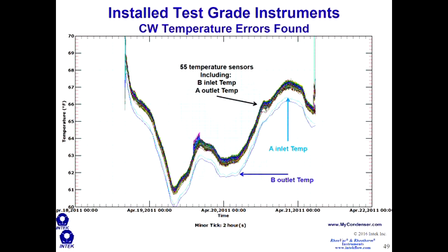Oh yeah, thanks, Colin. One thing to point out is that this data was obtained during no load conditions. So the cooling water is flowing and there's no duty to the condenser. That's the time to do this type of analysis. There's water flowing from inlet to outlet, no duty to the condenser, no temperature rise, and that's where you can compare your inlet and outlet temperatures. Thanks, Colin, for that important clarification.